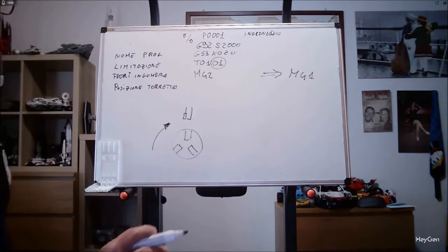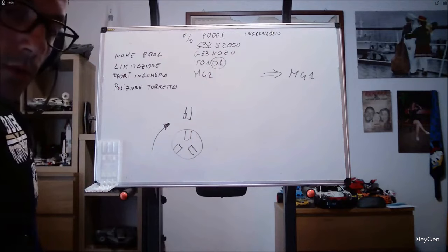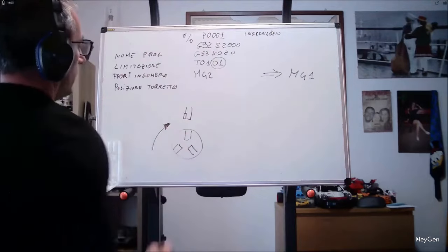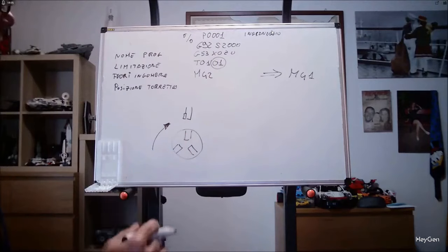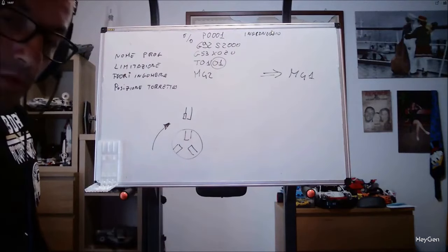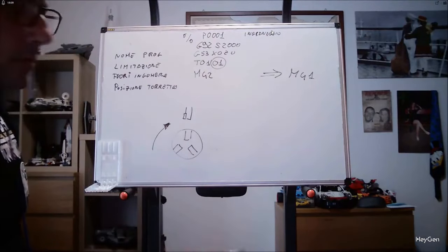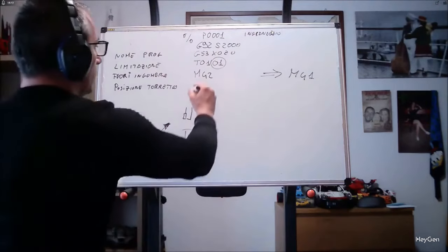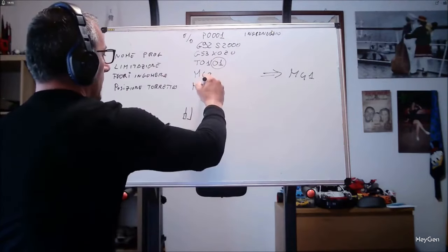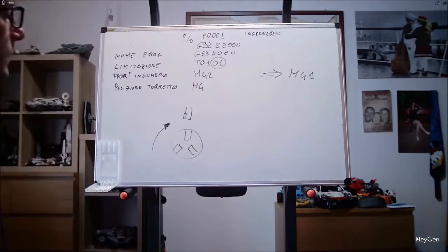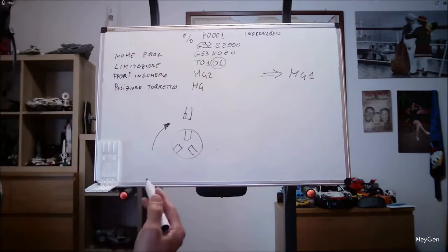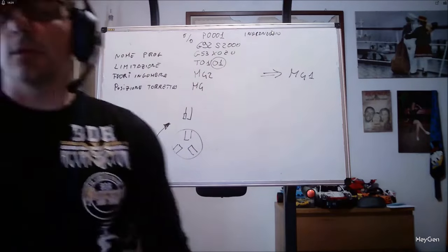This doesn't apply to all lathes because the Italians work in reverse, but for Fanuc, Siemens, or Okuma, the rotation sense for M4 is clockwise when looking at the turret.